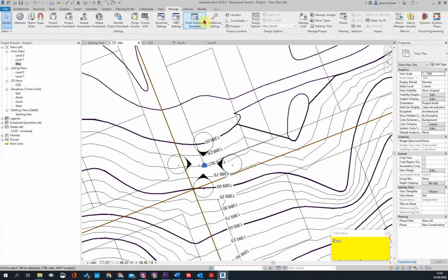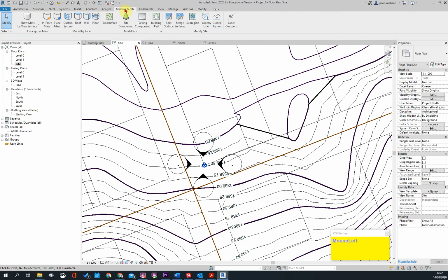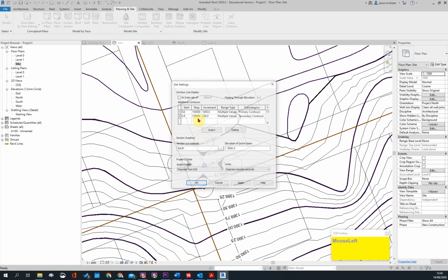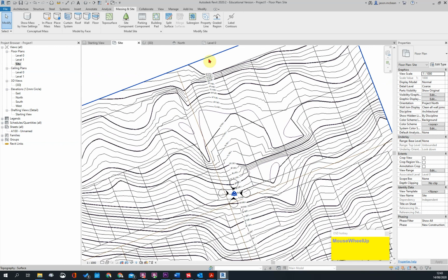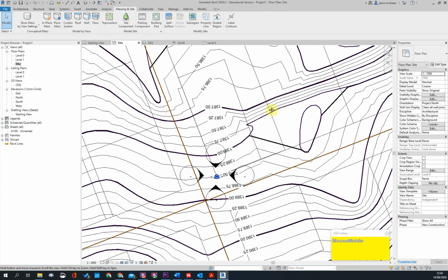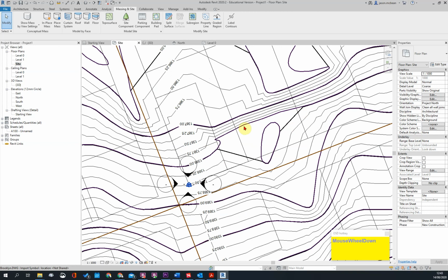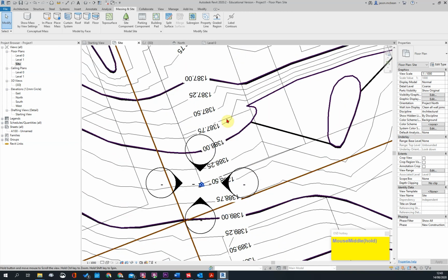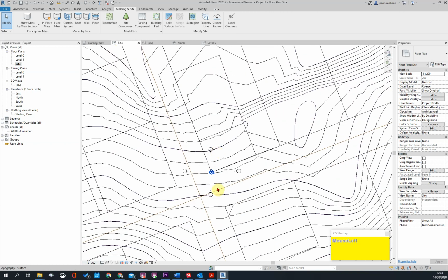So you need to go to massing and sites. So for example here, this one I could say minus 5000, and I can just leave that where it is. Select all of this, this will be minus 5000 as well. Okay, press apply. Okay, there I'm seeing all my levels. So here you've got your contours for the site roughly. There seems to be a plateau here, but now you've got your contours and the site's moved accordingly.